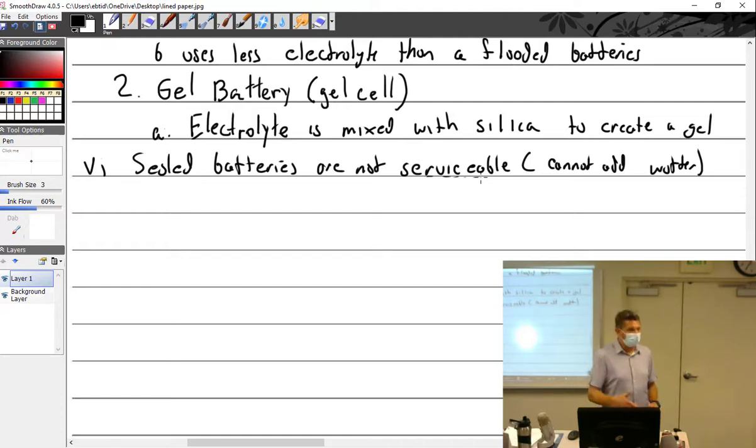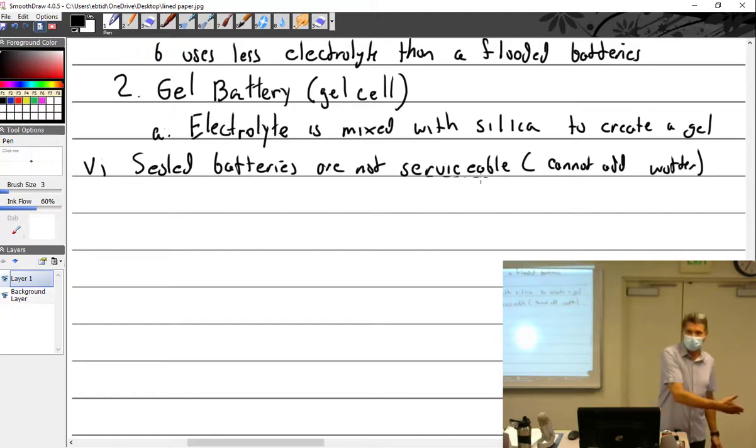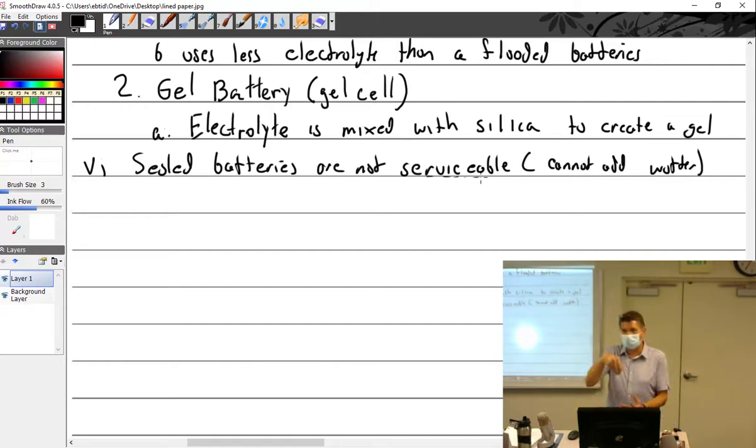But now when you buy a battery, even for the small planes, it's going to come with an entire manual of instructions for continued airworthiness. One of the big things you do every year now is a measured discharge on the battery. You do an inspection, verify its charge, and then do a measured discharge, just like you guys are now doing with that one Ni-Cad battery. You have to do that with the lead acid battery.